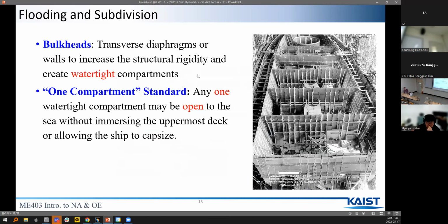When hull damage occurs, longitudinal static stability decreases and flooding occurs. If a compartment is flooded, the buoyancy provided by that compartment will be lost. Then the ship will sink deeper and its longitudinal center of buoyancy will usually move and cause trim. Once the deck edge goes into the water, transverse stability decreases rapidly.